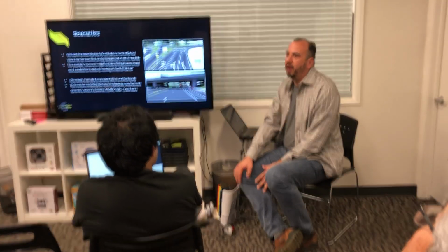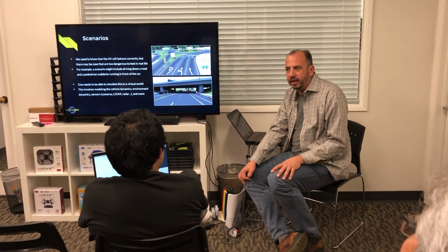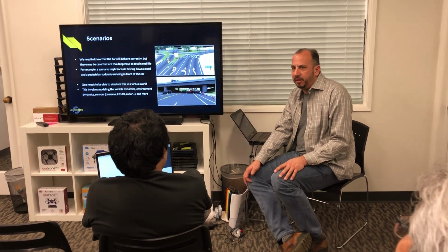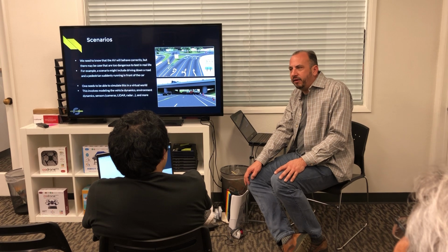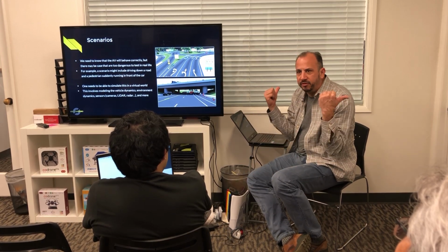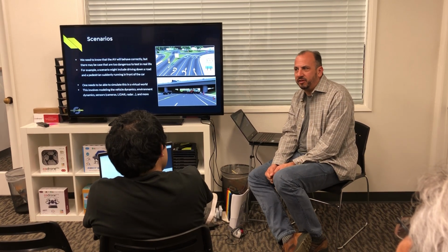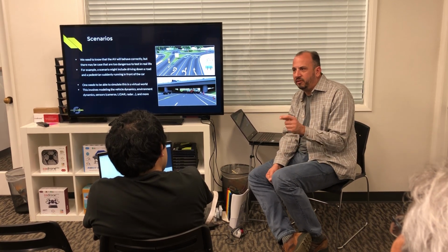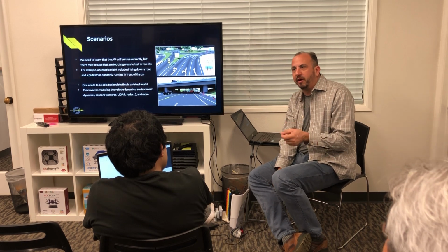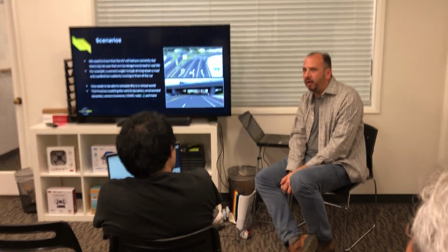The typical self-driving car these days will have maybe 4 to 8 cameras, maybe 1 or 2 LiDAR sensors, probably at least 1 forward radar, possibly side and rear radar, and very often 6 to 8 short-range ultrasonic parking sensors like that for detecting nearby objects.